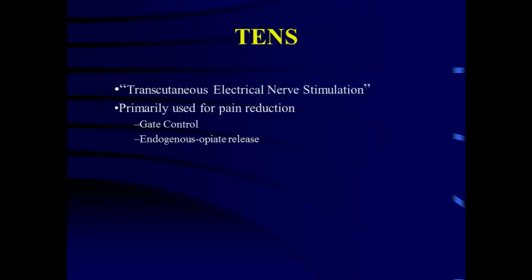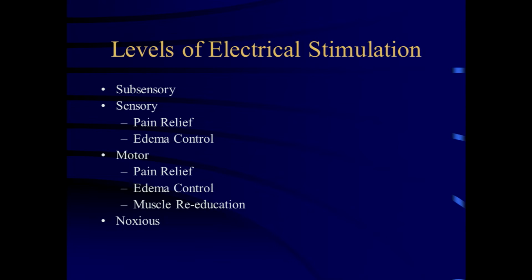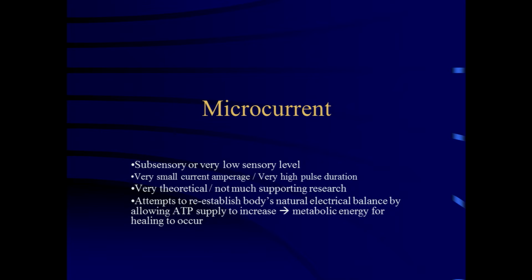You again look back at insulation engineering, what you're doing. You take a sample, and it is expected to operate at a particular voltage, maybe AC or DC. When you are testing it, you test probably around 2 to 3 per unit for the power frequency or DC, and go almost anywhere from 5 per unit to 7 per unit when it is in pulse. Same thing also. But what I am thinking with respect to frequency.